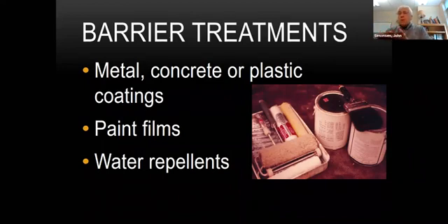Remember, your requirements for decay are temperature, moisture, and pH. Generally the high decay zone for wood is about 18 inches above and 18 inches below ground. So there's about 3 feet there.